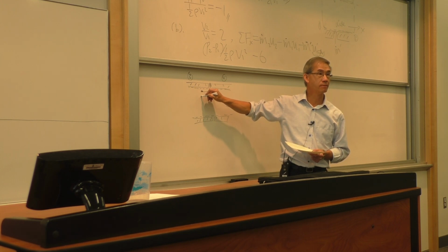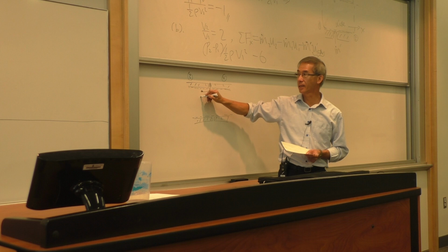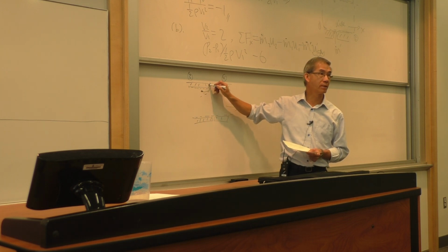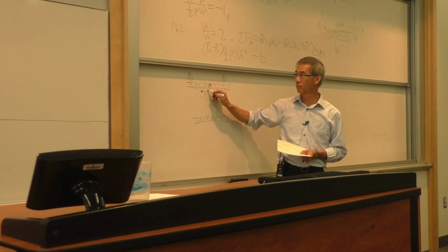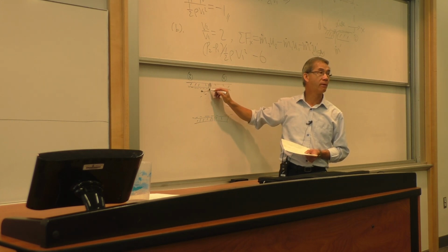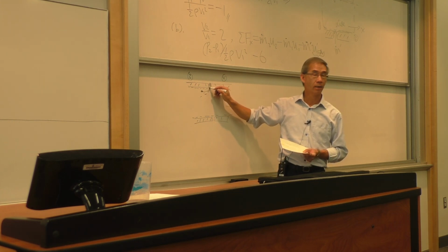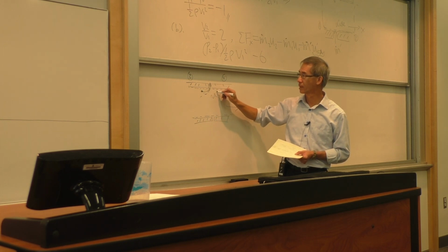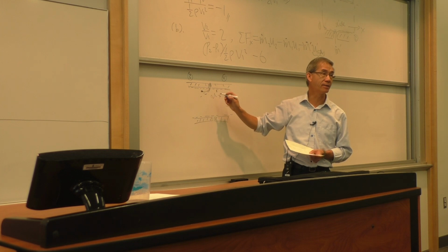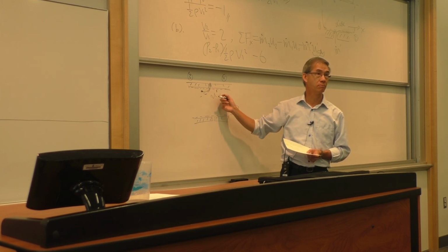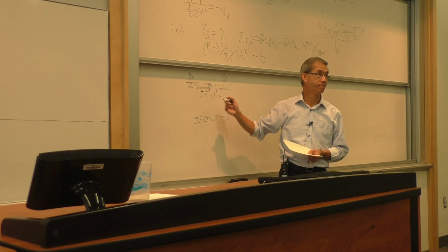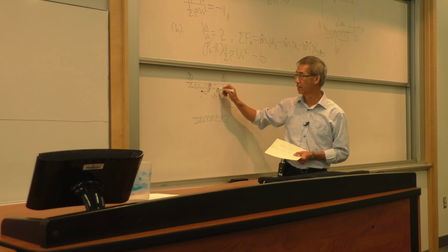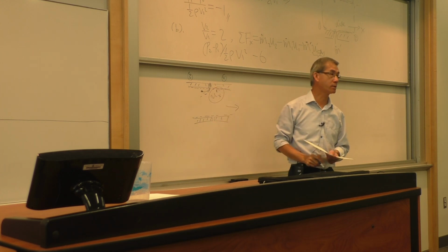The answer is yes. It's only after I enter that porous wall that momentum is destroyed. But at the moment that I leave my control surface, I still have, I call it Ux prime, a finite x momentum with me. And that has to be accounted for, and it's not zero.